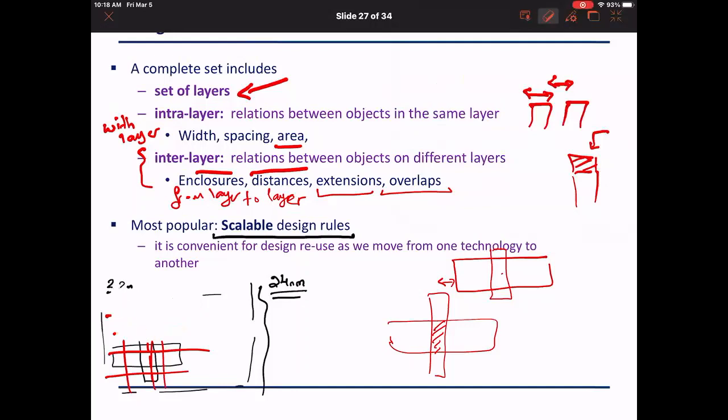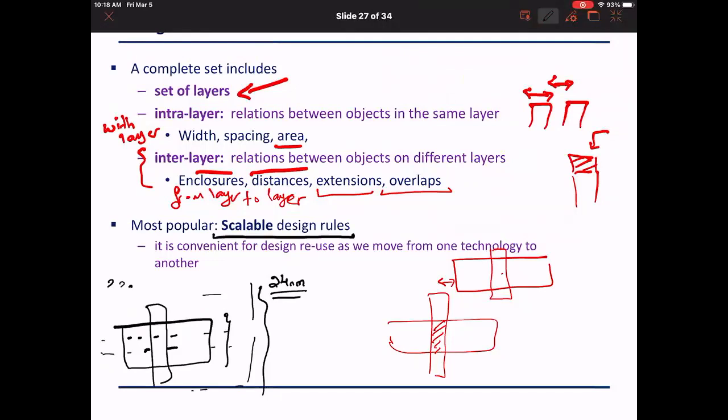This grid that I am going to draw on top of this transistor is going to be a function of L. I mean, if I make distances, let us say this width is 3 grid points. What I can do to scale is draw the same transistor, use the same transistor drawing, but instead of those 3 grid steps being, let us say, 100, I can say now they are 60.